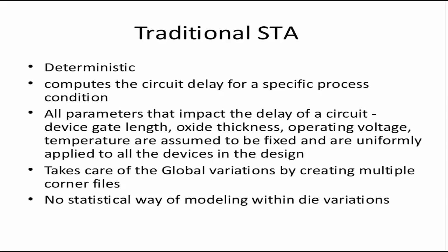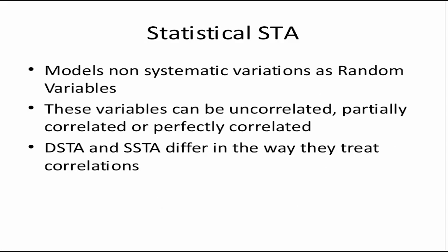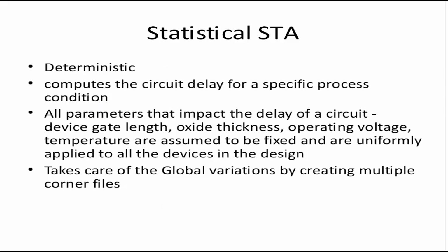Ideal is if people could model the variation, which is physically statistical, also as statistical in a tool. Let's see. This is what SSTA tries to do. It models non-systematic variations as random variables. Remember, non-systematic. Let's go back and see the categories again.